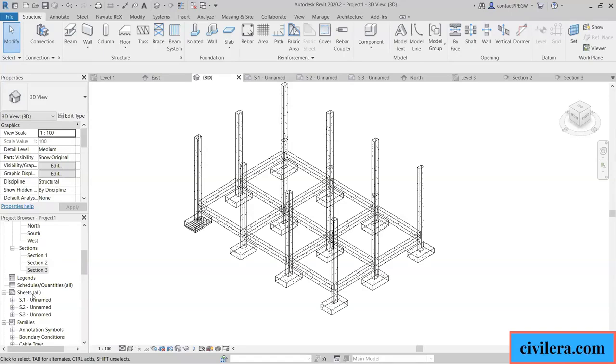I will not have time to get into the revision control in Revit. It's quite fantastic. Revision control in Revit is one of the best. It will never let you pick an old drawing. It will always flag up. So if you have S1 revised 10 times, it will only let you take the latest drawing. If you purposely want to take an old drawing, you can, but by mistake, it will never let you take an old drawing. So that way you are always on the safer side.